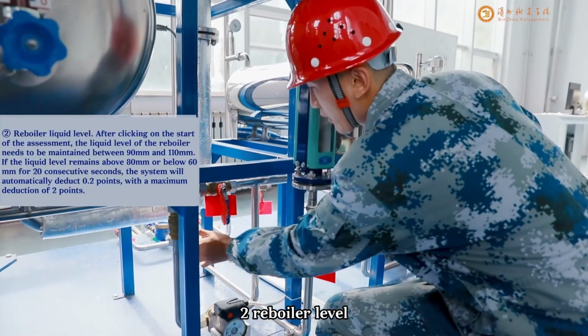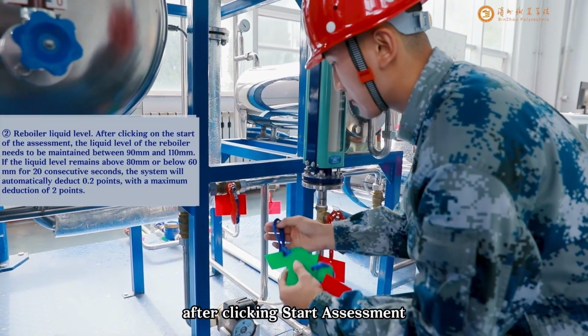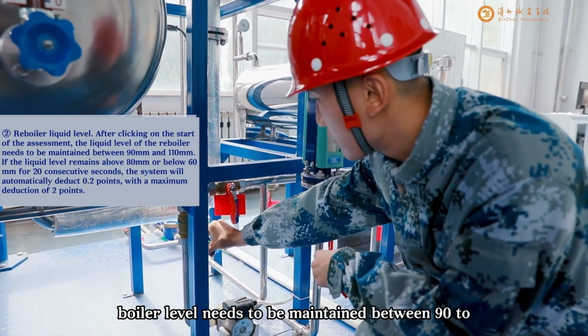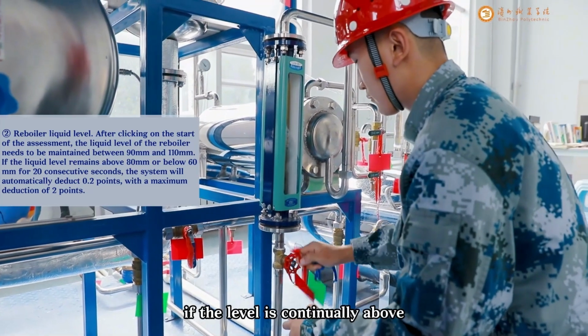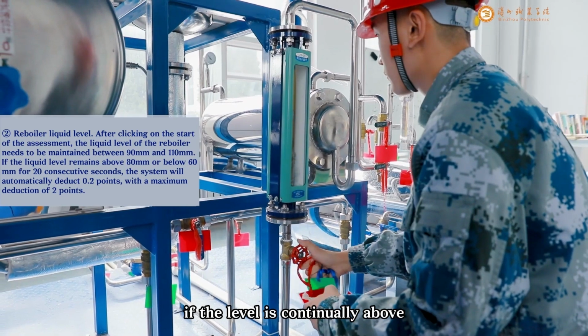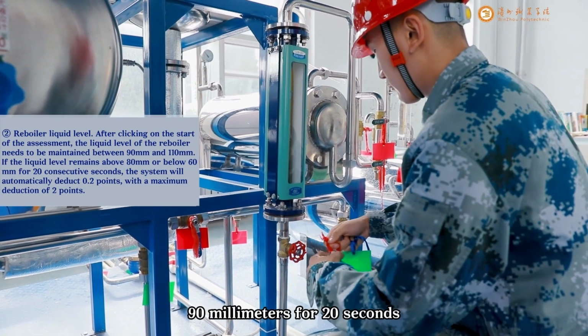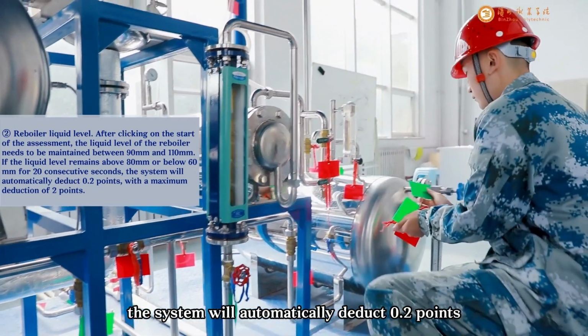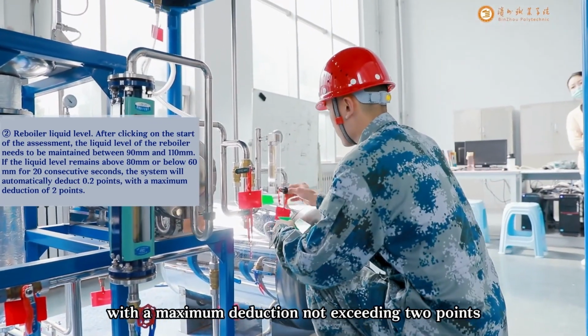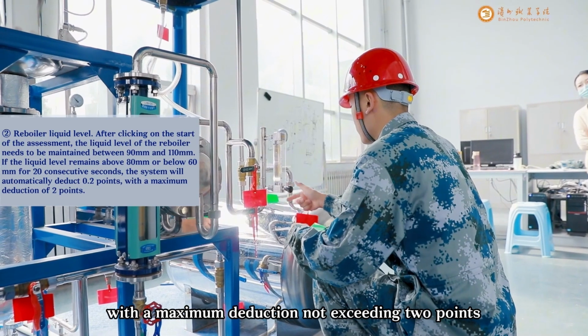2. Reboiler level. After clicking Start Assessment, the reboiler level needs to be maintained between 90 to 110 millimeters. If the level is continually above 110 millimeters or below 90 millimeters for 20 seconds, the system will automatically deduct 0.2 points, with a maximum deduction not exceeding 2 points.